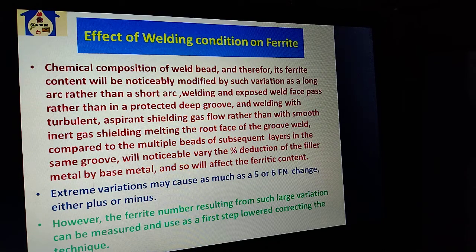The chemical composition of the weld bead, and therefore its ferrite content, will be noticeably modified by such variations as a long arc rather than a short arc, welding an exposed weld face pass rather than a protected groove, and welding with turbulent aspirating shielding gas flow rather than with smooth inert gas shielding.